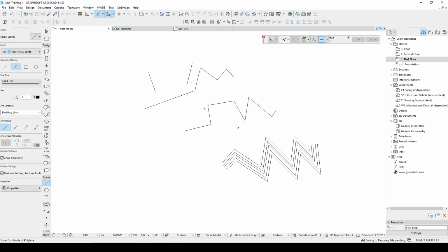So if I want to draw a line starting from that point, oops, back up. So L for line, hit the command, select. It's giving me the point in between, and then I can close that up. So that's a really cool feature if, let's say, you're wanting to find the center of a room and put a circle there.